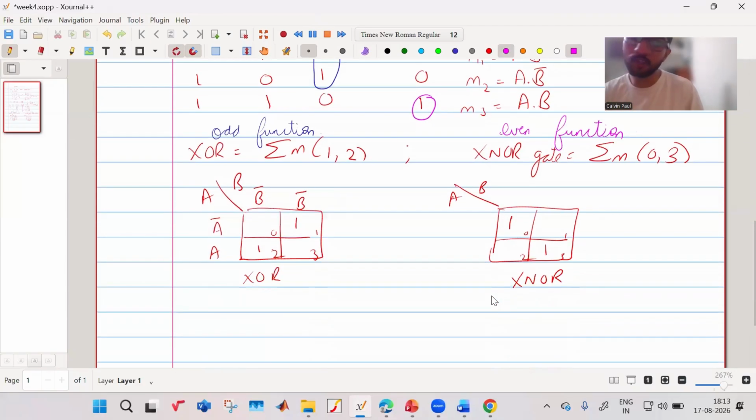When you look at the K-map for XOR gate or XNOR gate, what you will observe is that you cannot do any reduction or grouping. You're not allowed to combine like this. So these are certain characteristics of your XOR and XNOR gate, and because of this, people have found various uses of them.